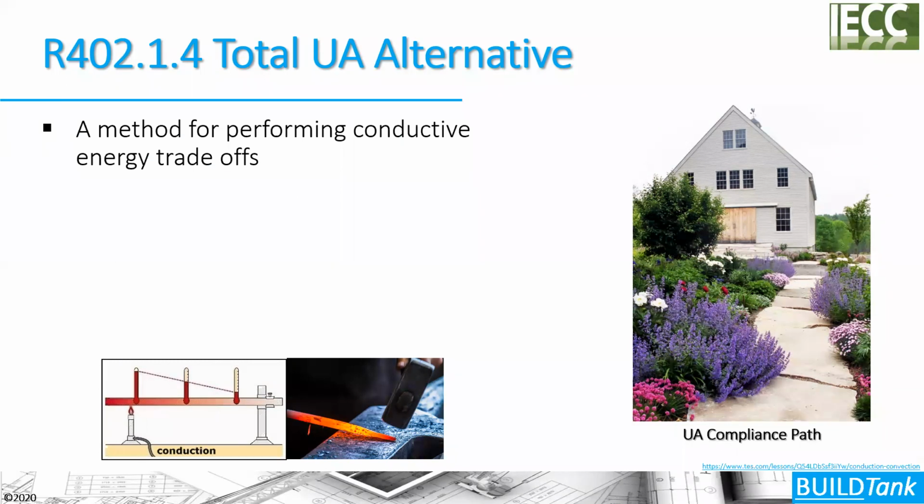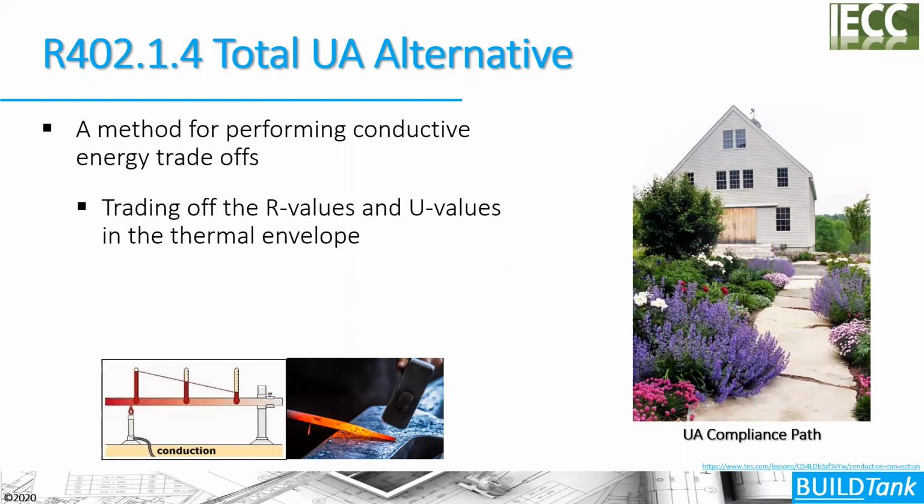values and U values. So if I'm a builder and say, you know, hell no, I've never put R49 in my attic, I'm going to stick with R38 in my attic, that's what I believe should be done, that's the most cost-effective thing to be done, that's perfectly fine, but they can't use the prescriptive pathway in the code. They have to move at the minimum to the UA trade-off pathway, or potentially to the other performance pathways in the code, in order to demonstrate that that trade-off actually works and is compliant with the code.